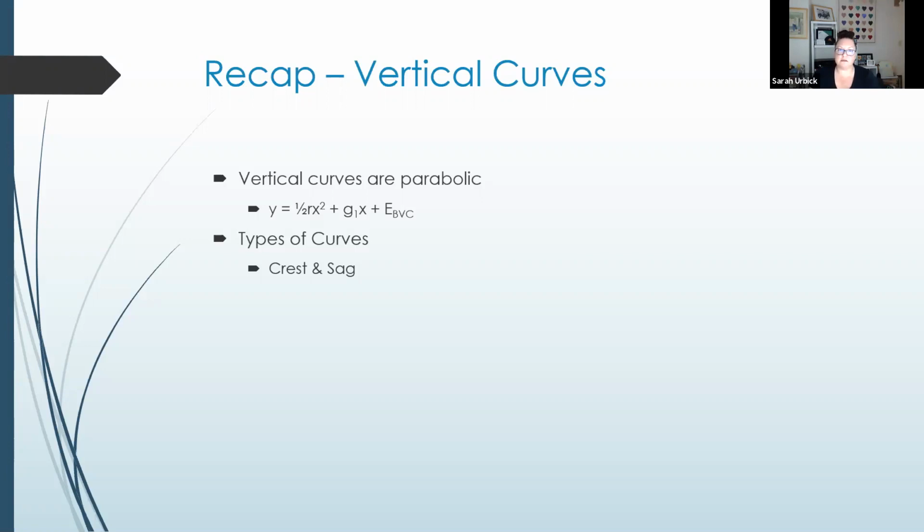Those five questions: what's the station at my beginning of vertical curve? What's my end? Where do my stations fall? Line that out, break it down into manageable chunks of one station units. Figure out what's my elevation at each station, what's my max, what's my min, and how far across is it, measuring from your starting point.